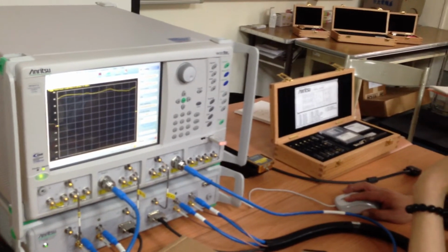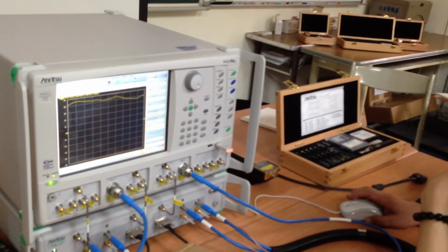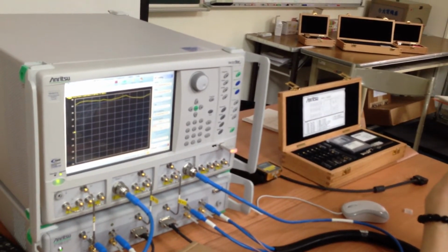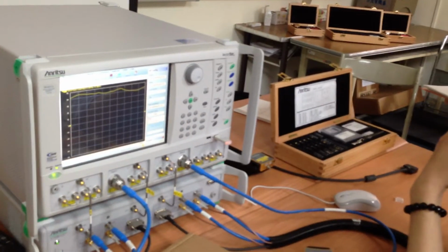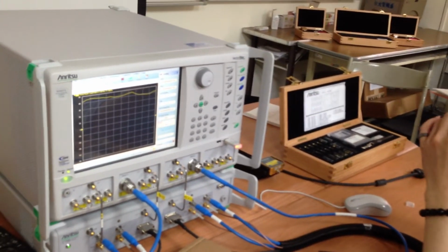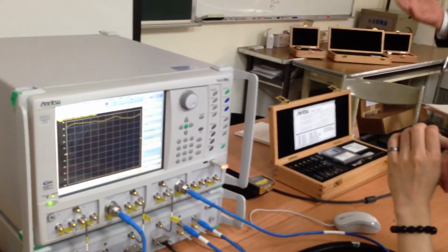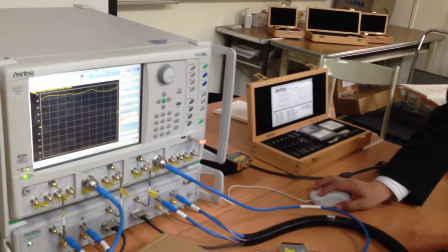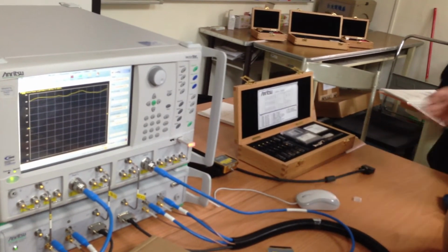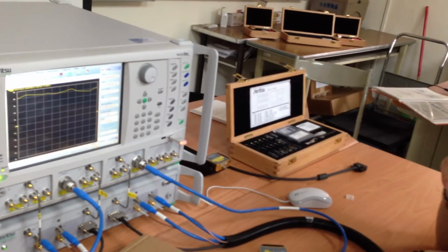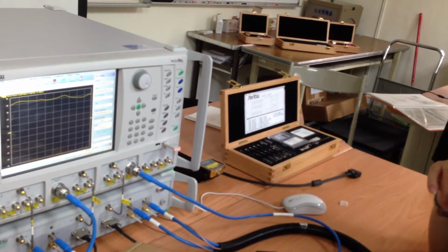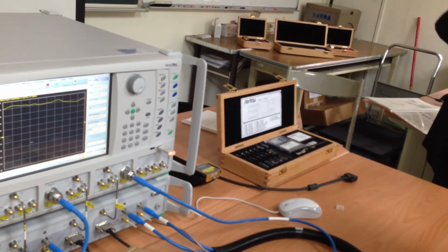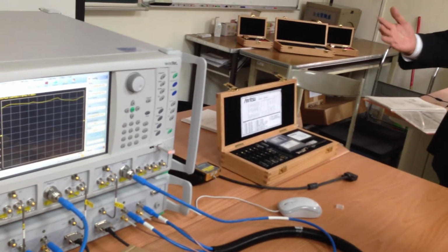But now the bandwidth is limited to 1 megahertz, right? Maybe it's for the noise figure measurement. A noise figure analyzer takes wideband data simultaneously, but this network analyzer measures a very narrow frequency window, then calculates the wideband noise data afterwards.